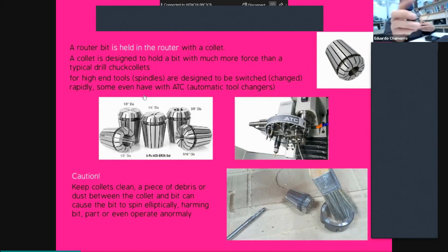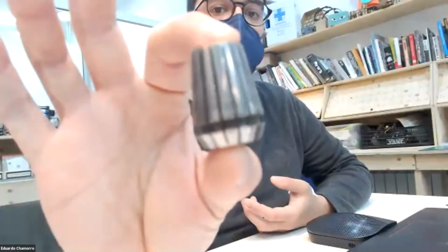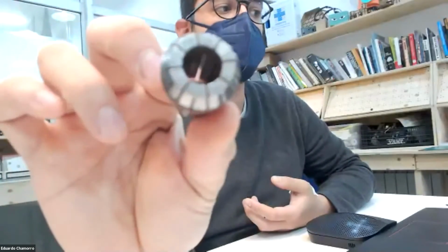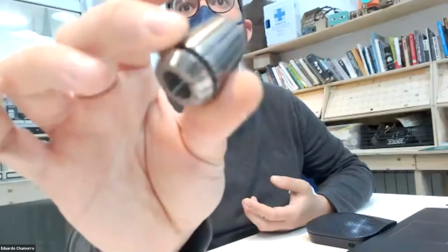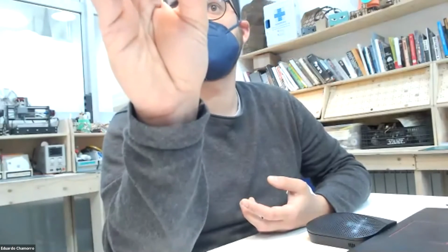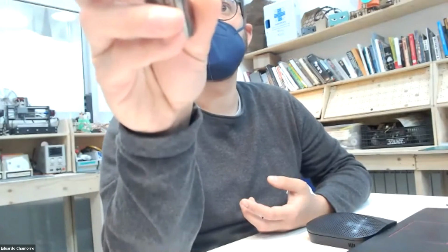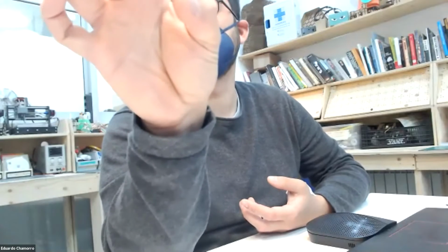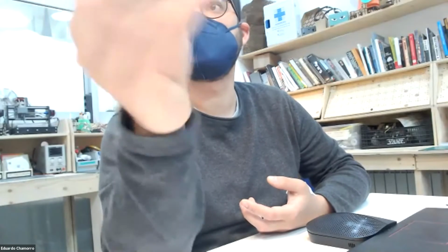They state first the exterior part. These are mid, big, small, depending on the motor you have. Smaller motors have this part really small. This one is a standard one, an ER25 size, which is more or less the standard size for a 1 to 3 kilowatt motor. They tell you the maximum size of end mill you can take. You cannot put end mills bigger than the collet size, so an ER25 can fit a maximum of 25 millimeter end mills.